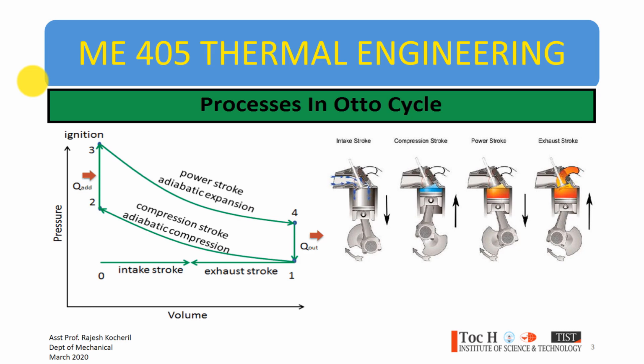Then after we feed food into our mouth, we close it. Then subsequently it passes through the intestine. The volume of the food is reduced. Subsequently, the temperature of the food increases. Same in the engine, when the piston moves from the bottom dead center to the top dead center, the volume is reduced, and subsequently work is done on the fluid. Here the fluid is air and fuel. It's a homogeneous mixture of air and fuel. As the piston moves up, the temperature and pressure increase as the volume is reduced.